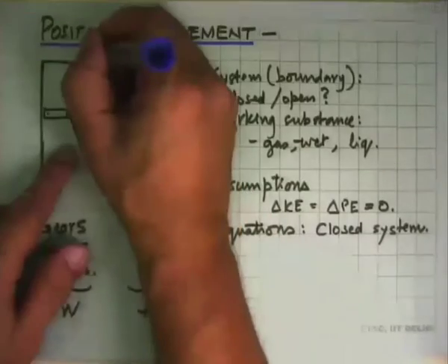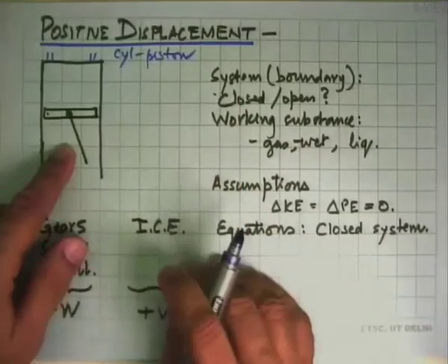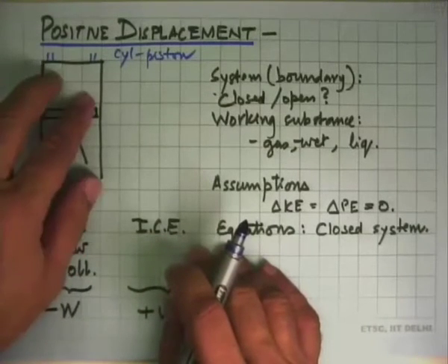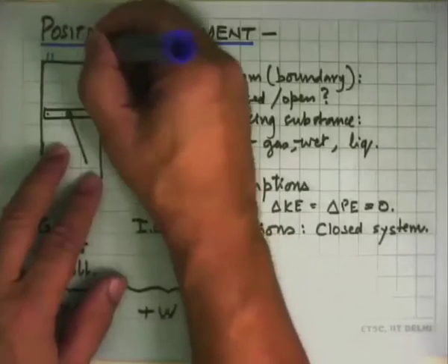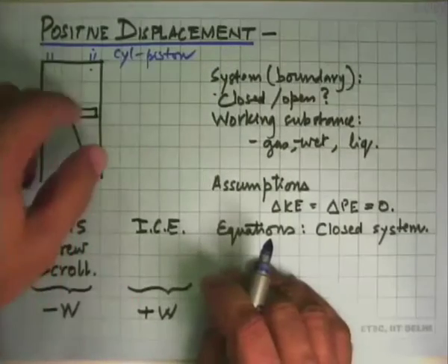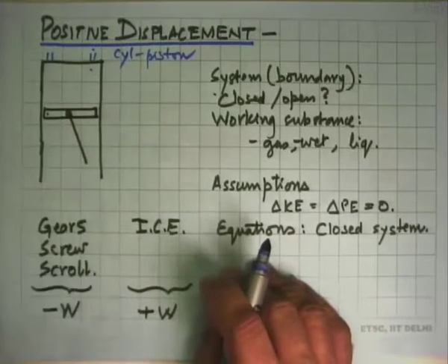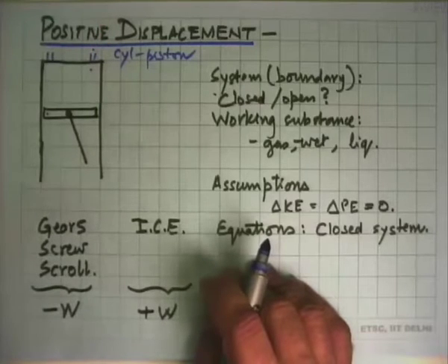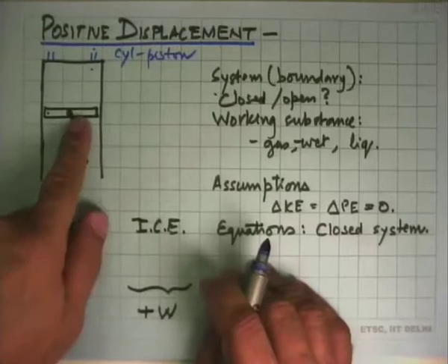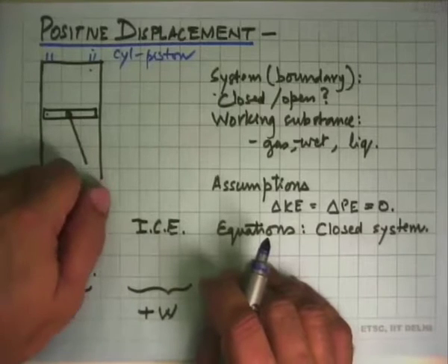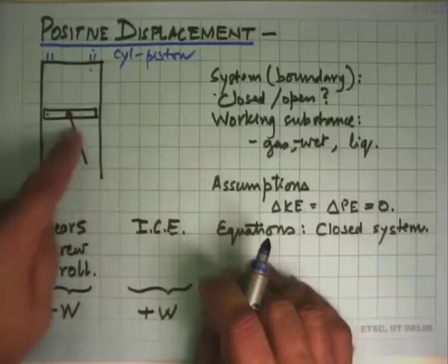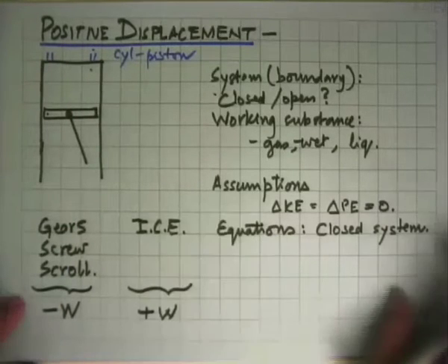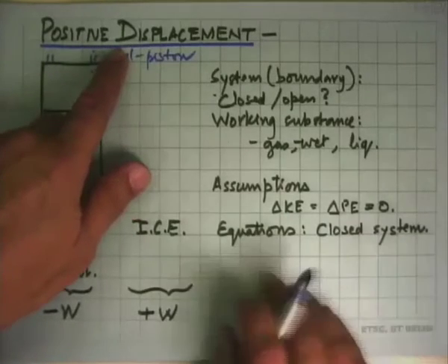For instance, if there is an inlet and outlet on this, and this is, say, handling air or, say, a liquid, then irrespective, once the fluid is inside this, the piston will compress it, and the moment the pressure inside is more than the pressure outside, across between which there is a valve, it will push it out no matter how much pressure is there. So in the worst case, if the outlet has been completely closed, the piston will still try to push it out. If that doesn't go out, the pressure will keep increasing, then something in this will break. That's the critical thing of positive displacement devices.